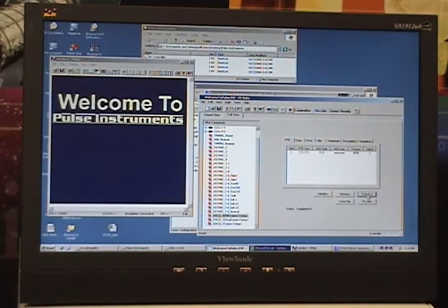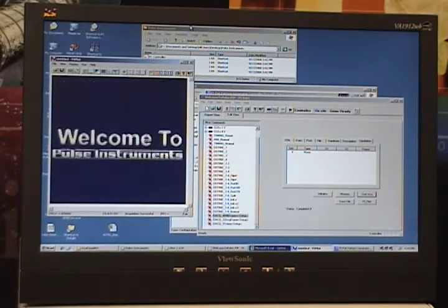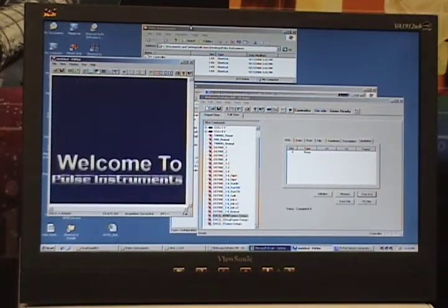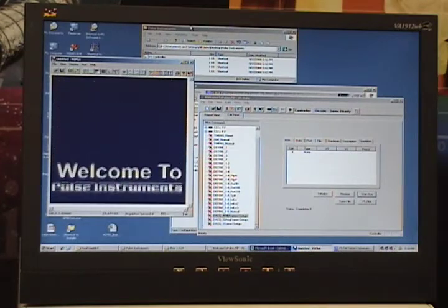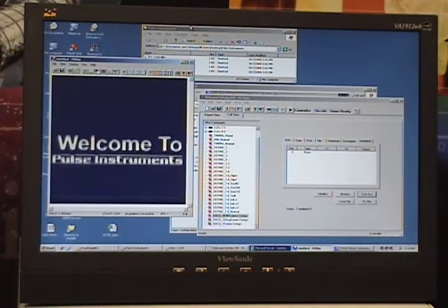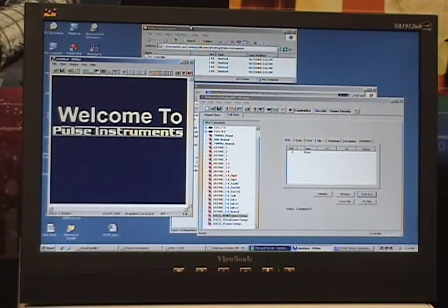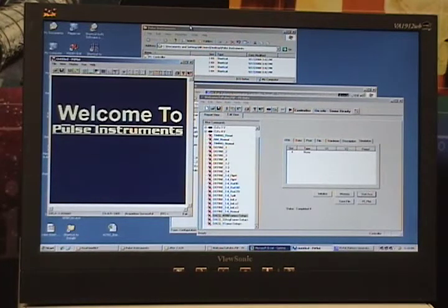Once the data has been DMA'd to CPU memory, we can play it back or examine any particular frame. This sample pattern was designed to move the logo by exactly 1 pixel on each successive frame. So by paging through the file, 1 frame at a time, we can verify that we have captured all 4,096 frames without missing a single frame or a single pixel.